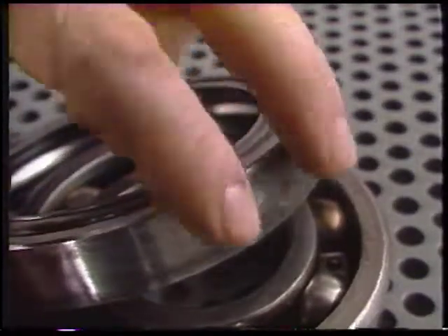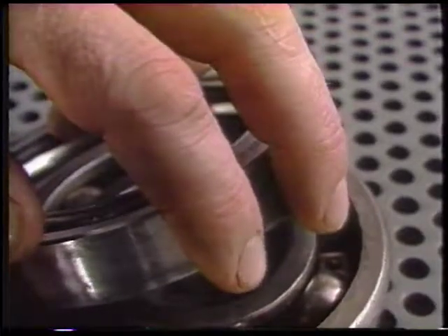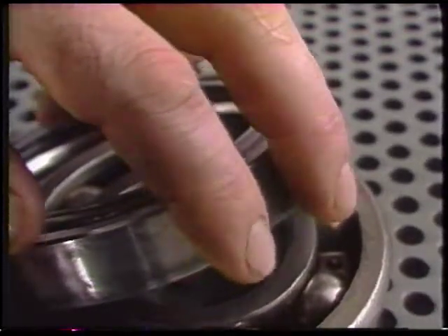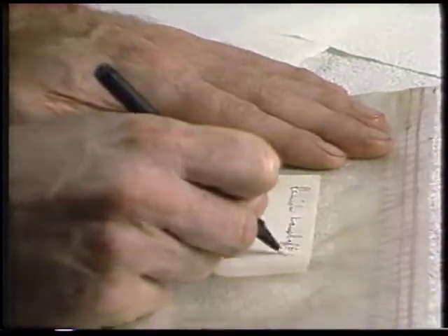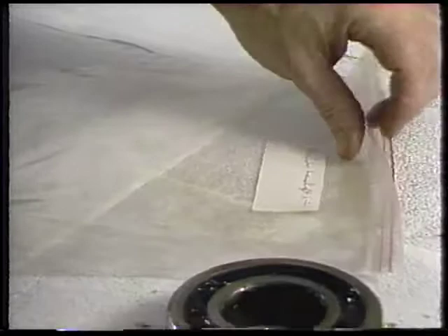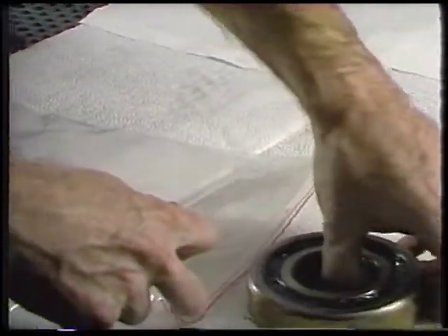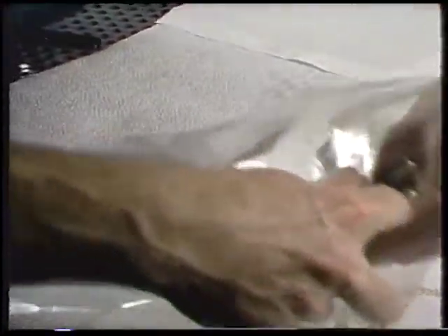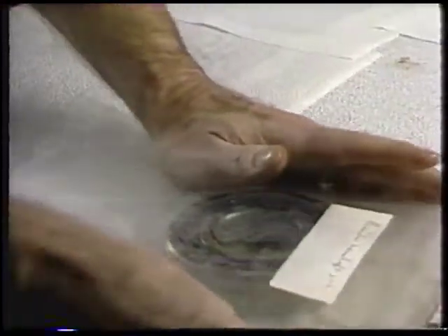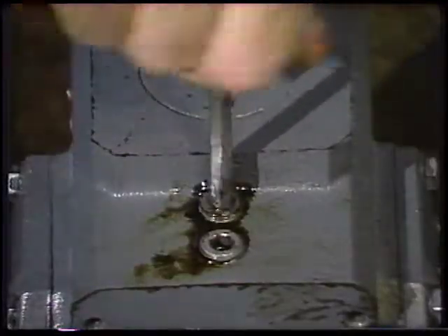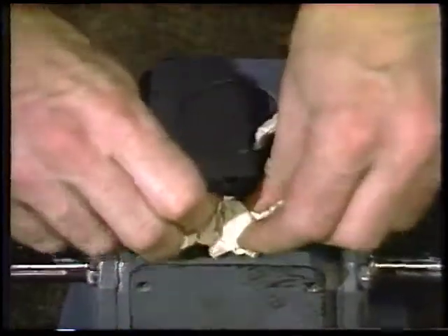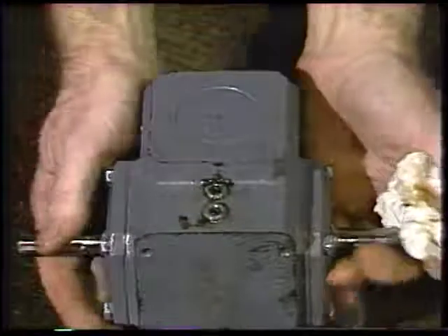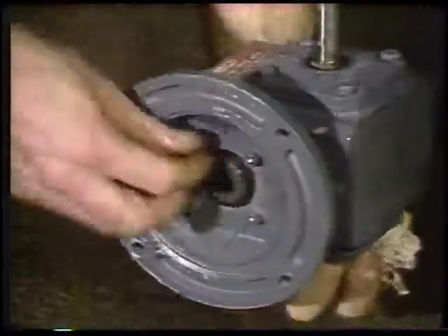Bearings rust easily. Since perspiration and skin oils are usually acids, even fingerprints can corrode a bearing. If a bearing is removed from equipment and stored for any length of time, pack it full of grease and seal it in a plastic bag with a label. This prevents air and moisture from coming into contact with the bearing metal. If equipment will not be used for a long time or is being transported, make sure the bearings are thoroughly lubricated. To keep all parts well lubricated, it is good practice to invert the equipment by hand occasionally.